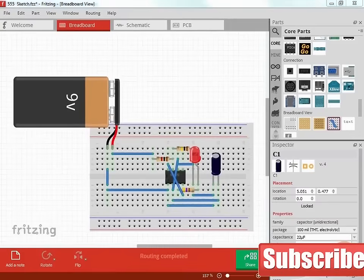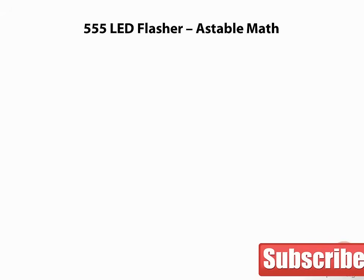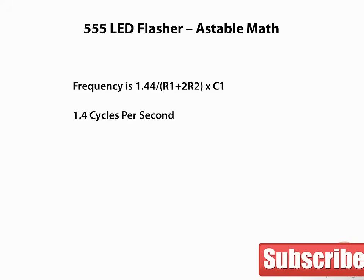There are lots of ways to make the connections. You'll get the hang of keeping things simple and neat with some practice. For our basic astable circuit, the frequency of the oscillations is given by the equation 1.44 divided by (R1 plus 2R2) times C1. We chose these values for our circuit so that the frequency of the flashing is about 1.4 cycles per second.